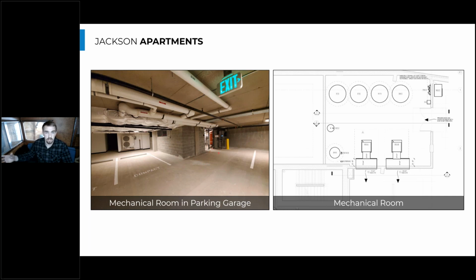So we have air that needs to be pulled in through the heat pump water heaters, and the heat is extracted from that air to then use that heat to heat the water. So these heat pumps are consistently cooling that air down by pulling the heat out of it. So we want to make sure we're providing them with fresh air and the warmest air possible, so then they can most easily extract the heat out of that air.